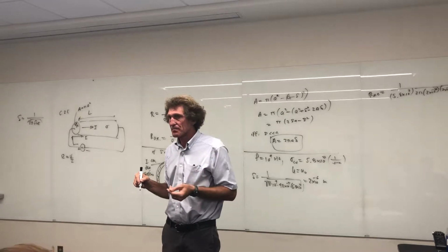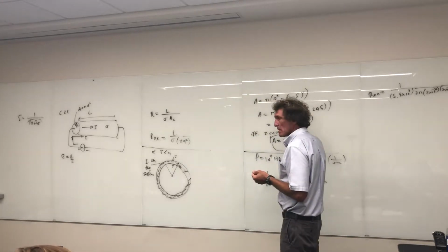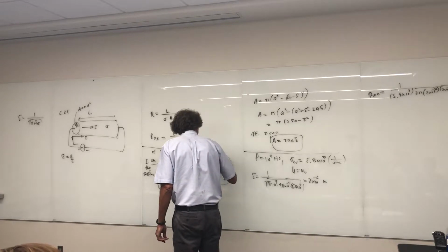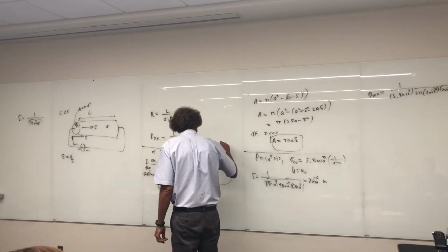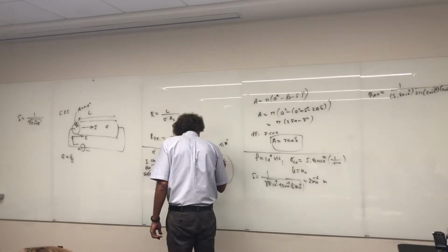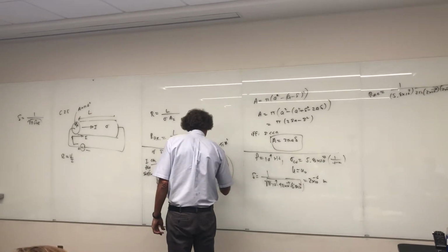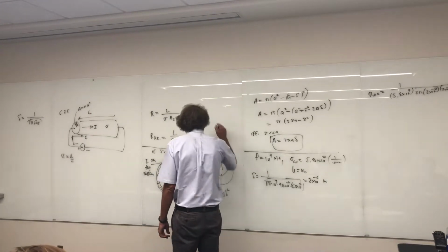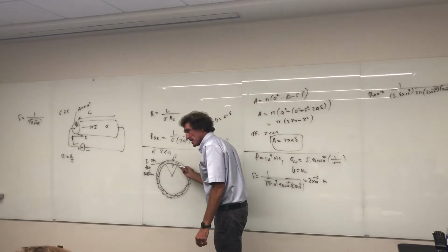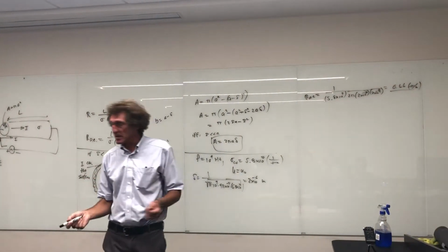Any questions? Yes, sir. For the first area formula right there. Could you explain that setup, please? Sure. What is the area of a circle of radius a? Pi r squared, or pi a squared, right? All right, now, what's the area of this circle right here of radius b? That would be pi b squared, right? Well, b in this case is just equal to a minus the skin depth, because you go out, but not all the way to the edge, you go out right to here. And that distance would be a minus the skin depth, that's all it is. Okay.